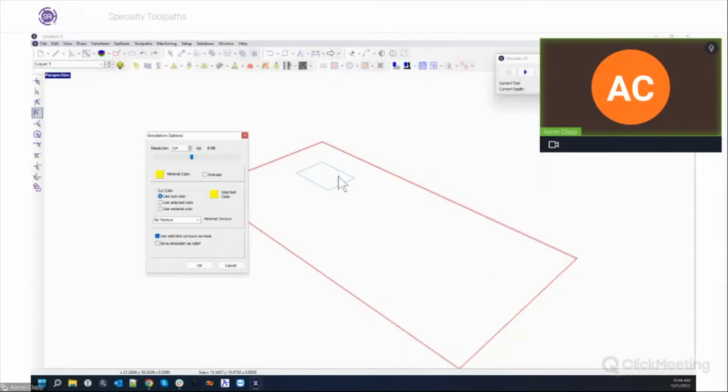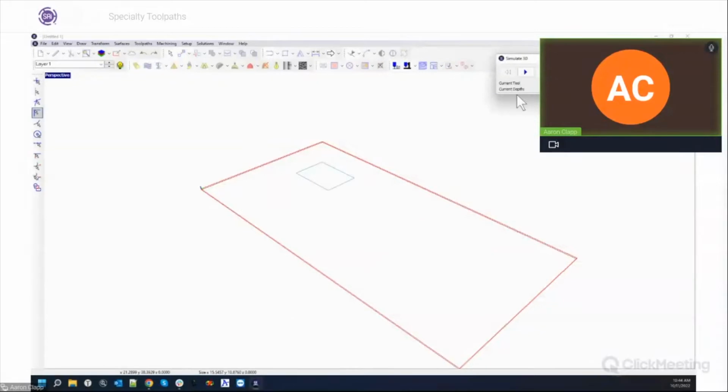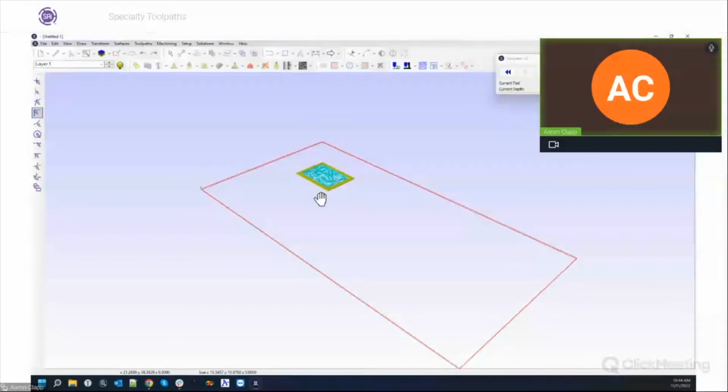I just need to preview this area. That allows me to stay lower on the megabytes. If I uncheck that option, look at how it jumps up. This now becomes an extremely difficult thing to process. So using that allows you to bump up the resolution quite a bit, much better quality preview, but not sacrificing a ton of processing time. So that's just a little tip there.